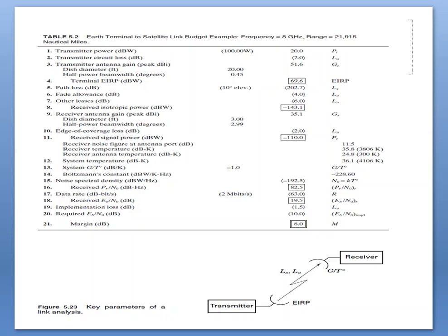We form the receiving figure of merit ratio G/T by combining the gain of the receiving antenna G with system temperature T. The ratio is placed in the left column as the parameters of interest rather than the middle column. This is because G is accounted for in link budget item 9 and Ts is accounted for in item 15. If G/T were placed in the center column, it would represent a double tabulation.